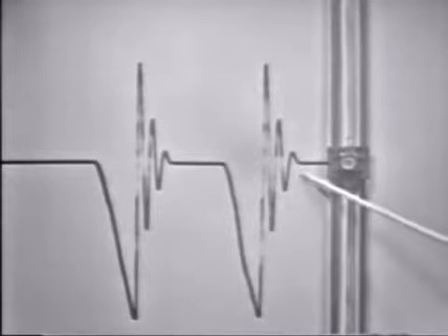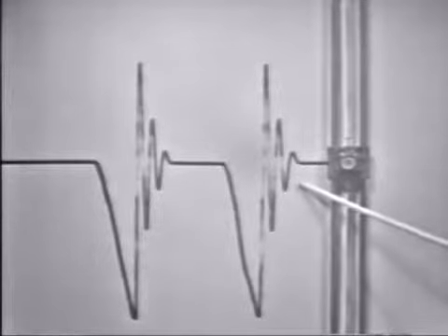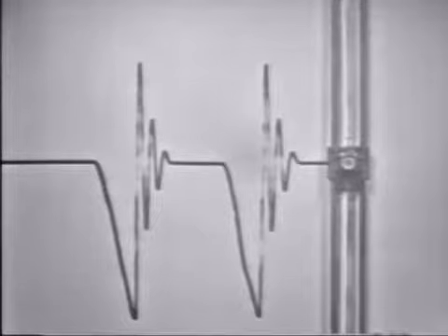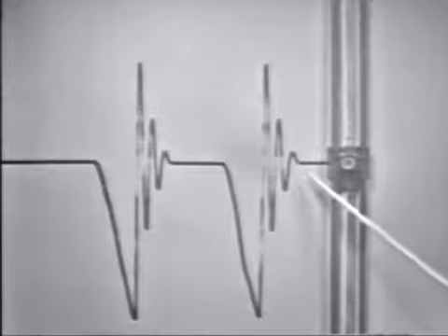What causes this damping action? What causes the decrease in amplitude? Well, in this case, the action of the oscillator is gradually diminished by the friction of the slide, the friction of the pen on the paper, the force of gravity acting on the weight, and the resistance of the rubber bands themselves. In short, the diminished amplitude on the graph is caused by inherent resistance in the oscillator.